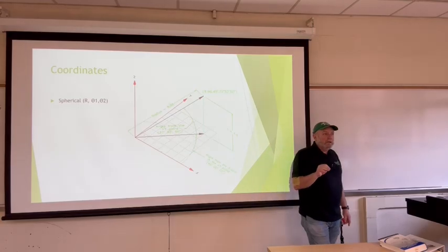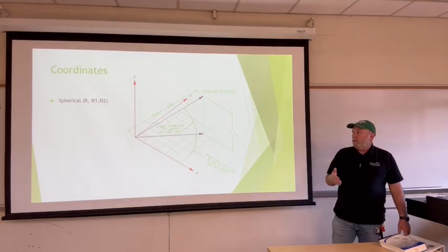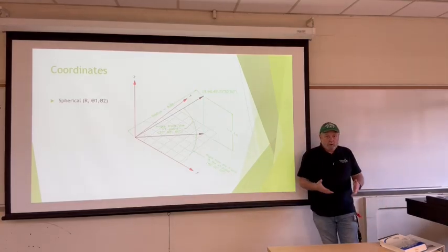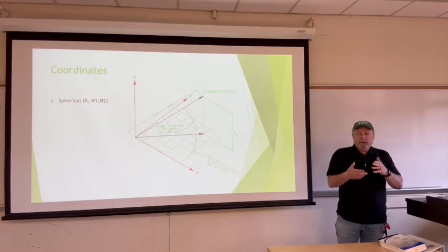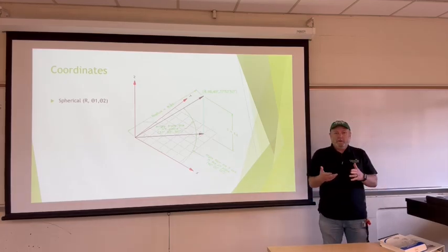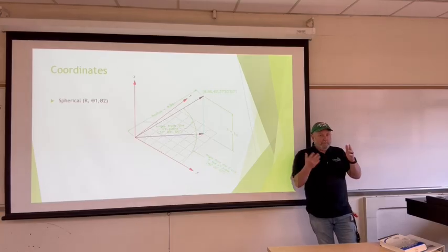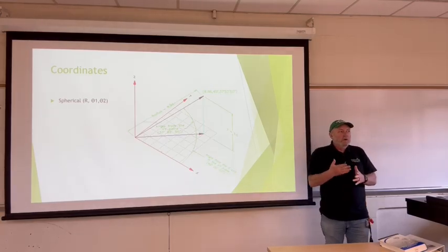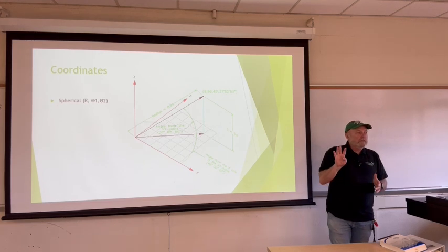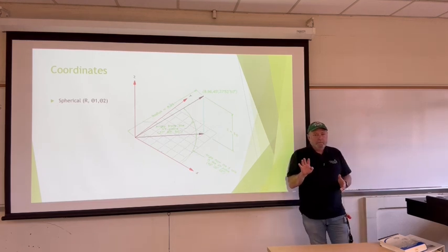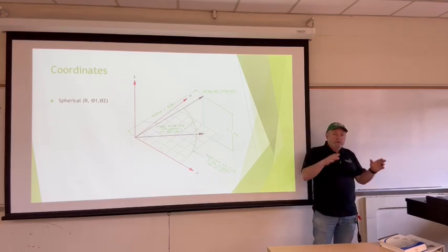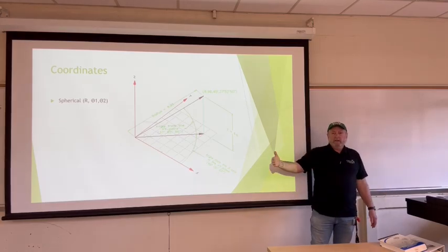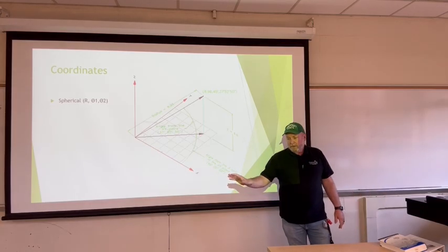So what's really important moving forward when we start publishing our coordinates, our latitudes, longitudes, and things, we need to add a new component to our coordinates. Right now we basically do a northing, easting, elevation or a latitude, longitude, and height. We are now going to have to add a fourth component to that, which is going to be time, meaning when was this observed?